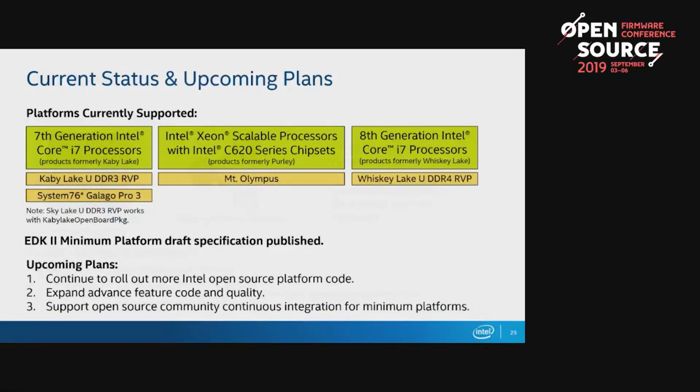An example here is we're putting out a new driver that can actually do BIOS debug messages over the HDMI port. You can use the I2C lines that are normally used for EDID, and we can send BIOS debug messages over those to a Bus Pirate that's operating in slave mode. We've also done things like move a lot of the build tools that we use to Linux and test them as well on various Linux distributions. So we're trying to make this all more friendly and easier to use across the environments.